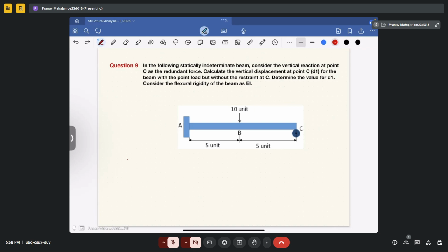So using the force method, the question is already telling you the steps to solve the problem, but in the journal it is not available to you. So we will start with the basic things that we are expected to calculate. First, we will calculate the degree of static indeterminacy. So in this case, you have the number of unknown reactions.